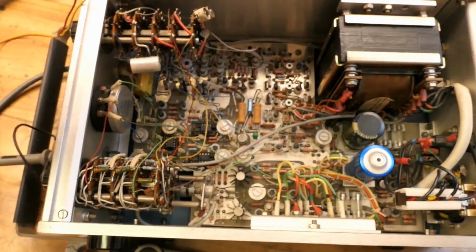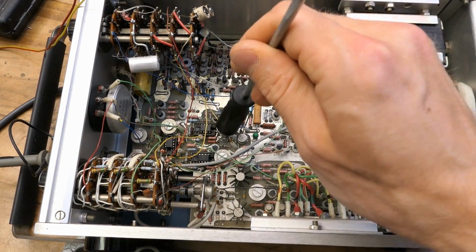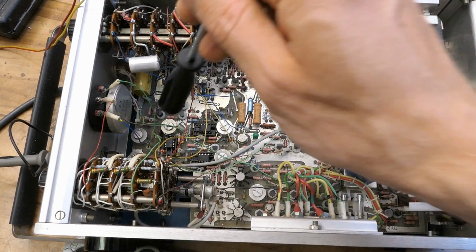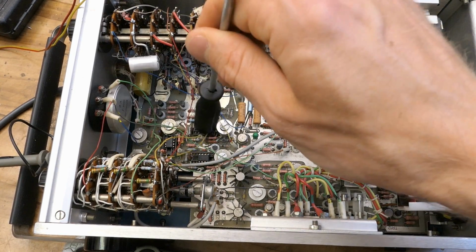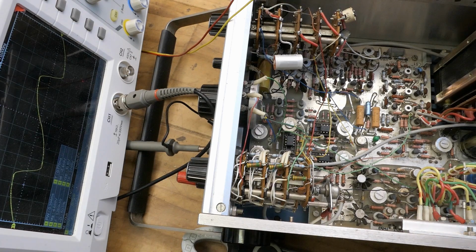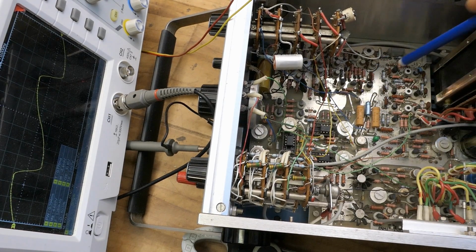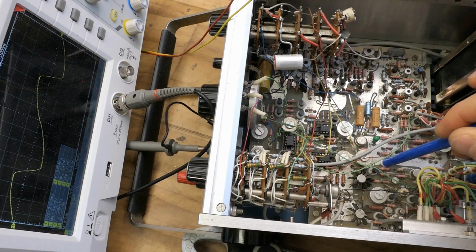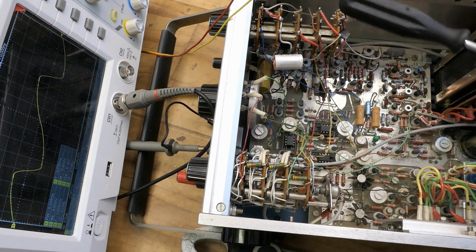Now let's try some dumb techniques, like tapping these trim pots and watching the distorted waveform, if it maybe changes or improves, or maybe the OpAmps have a poor contact in the sockets. There could of course be some mechanical problems, some poor contacts, bad solder joints, trying to flex the board a little bit, if it has any effect, or basically tapping the thing.